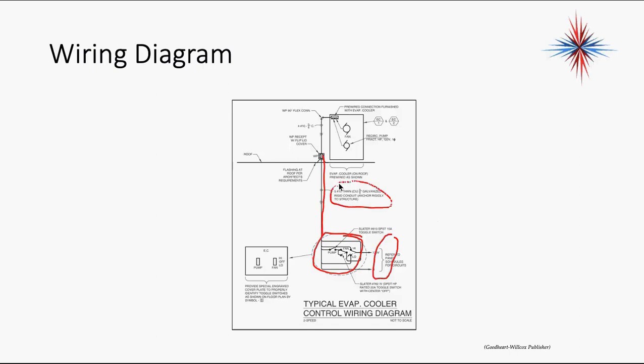There's a number 5 or 5 number 10 in a 3/4 inch galvanized rigid conduit. And then up on the roof, there's going to be a receptacle with a lid cover. And that's how the fan and the pump install. So it's showing how the equipment is wired into the main, and it shows it in enough detail that an electrician can wire this.